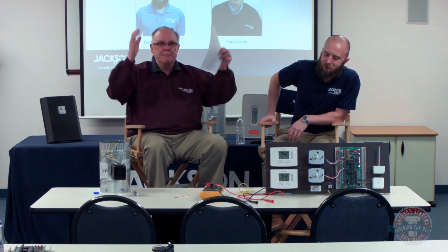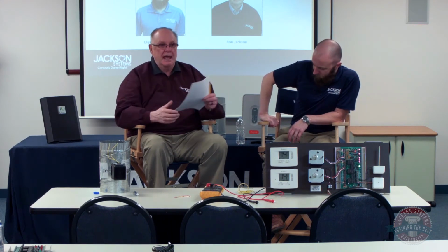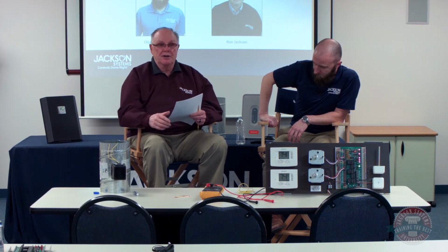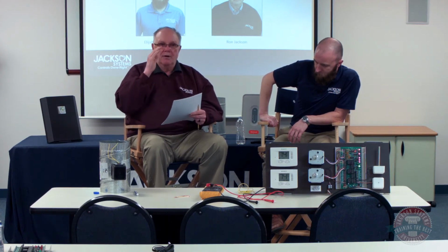If you have an upstairs, everybody knows warm air is going to rise. So if you have return air, there's no question that some of the warm air that's rising will be pulled into those rooms, and if that happens and you're doing setback, you're not going to get as aggressive a setback. I had a 2-story home. I wanted to get the most aggressive setback, save the maximum amount of money. I didn't want to close the doors. You can close the doors and accomplish the same thing.